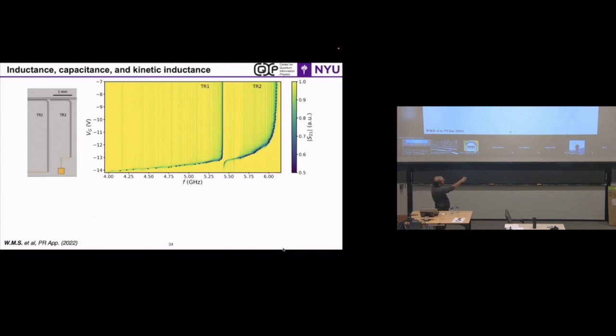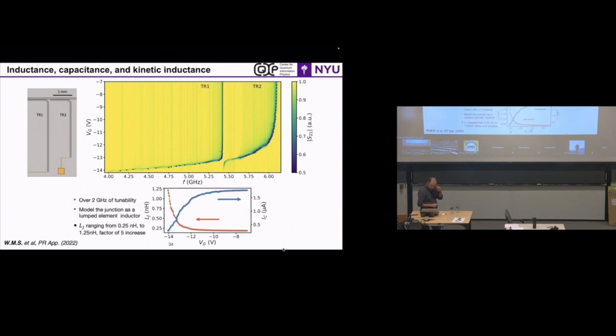And now you see that the tunable resonator, I can tune it from 6 gigahertz to almost maybe 4 gigahertz. And the fixed one is at 5.3, 5.35, and it shouldn't change with gate voltage, as it doesn't. But then when the two resonators see each other, there is an anti-crossing because they're coupled through the bus line. And you can basically find out what this crossing is, and I will show you in a second.